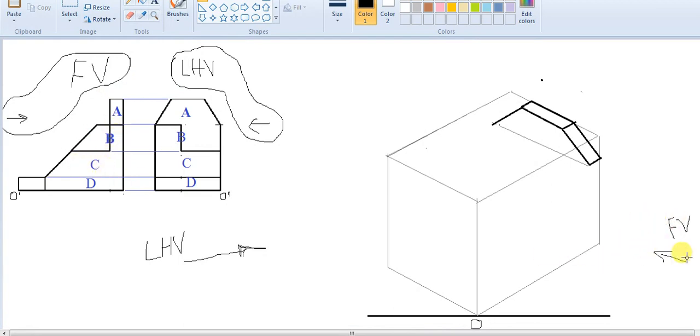So for front view, this part going down is the nearest one, and hence this remaining part is away from the observer. So that is how it will proceed. There is a certain distance, it is carried outside and then it is tilted. However, on this side it is coming straight down. You can see it is a straight vertical line. It is coming down up to the bottom because there is no bifurcating line present between C and between D, and hence we will continue it like this up to the bottom.